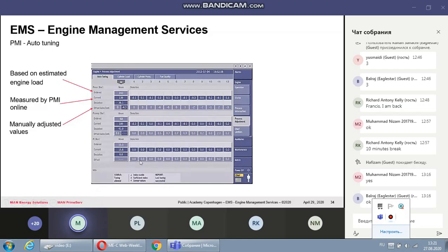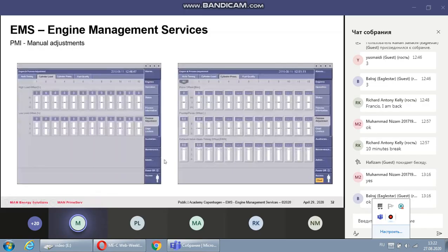Okay, now what you have to do first is balance between all the cylinders. So how do you balance all the cylinders? Click on this button, big button. When you click on this button, you will have a display here: tune PI values or all. Do not use the button all, use only PI. The moment you click the button PI, all these parameters will change here, and which you can also see on the screen. It will also change the values here.